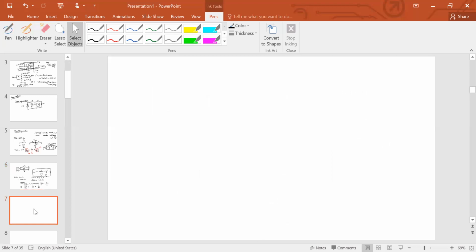So having covered this, it is now time for us to move into rotational systems, rotational dynamics. So here, the main difference will be that instead of a force being applied, what will be applied is a torque. You will still have a spring, which will not be a linear spring, but a torsional spring. You will still have a dashpot, which will resist the rotational motion instead of the translational motion, so that I may write this, where T is suppose the torque applied.